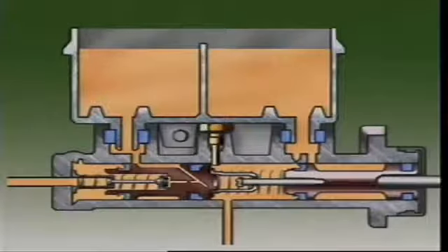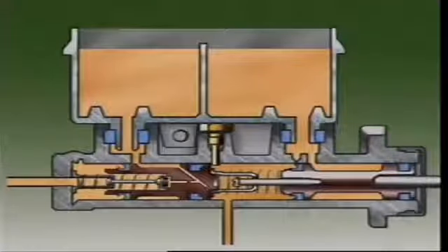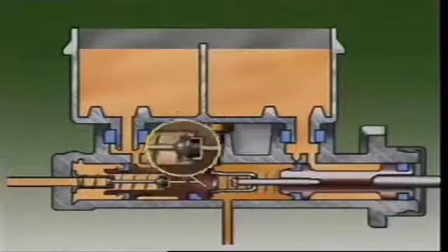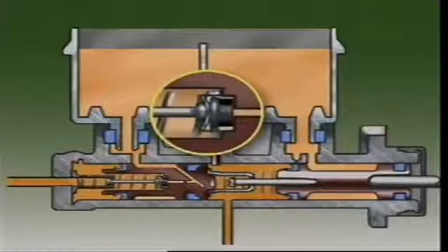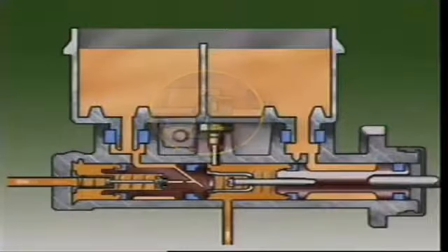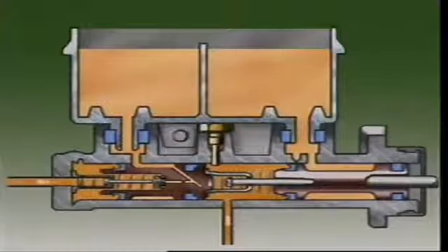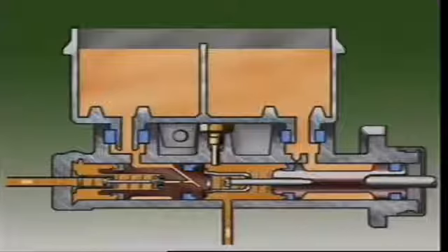When the brake is applied, the primary piston moves, which closes its compensating port. Fluid pressure in the primary circuit rises. It acts with the primary piston spring to move the secondary piston forward, closing the center valve. Pressure builds in the secondary circuit. Pressure keeps building in both circuits and applies the brakes in both circuits.